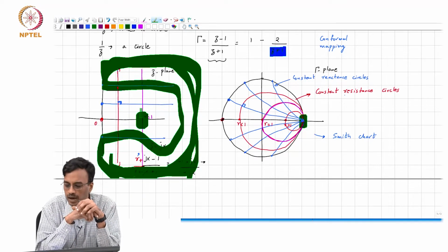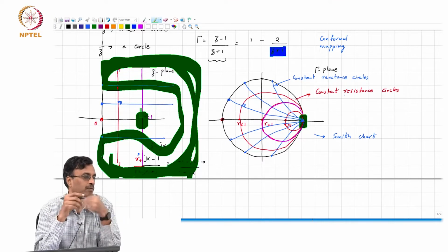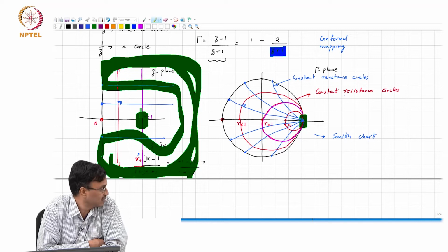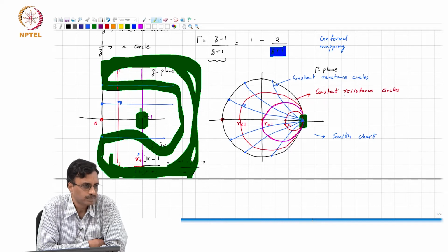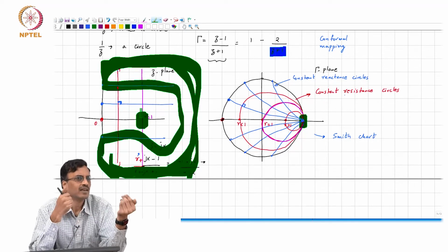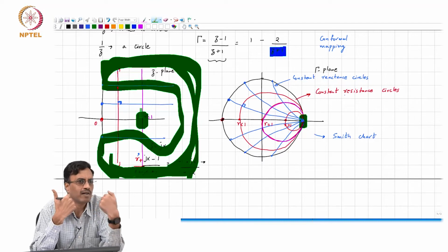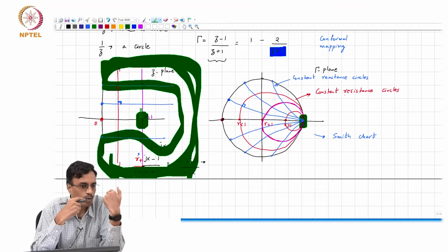That was, and still remains, a very important thing, called impedance matching, where the idea, as we have seen yesterday, is to minimize the amount of power reflected by the load. You want it to absorb everything.